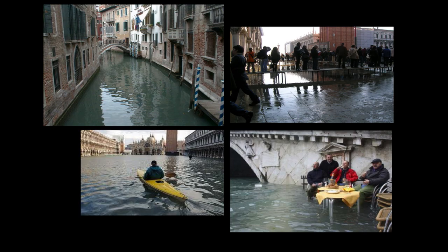Furthermore, the mud upon which all of these buildings have been built is getting compressed. Yeah, you can put down pilings and you can be very careful about your foundations, but at the end of the day, we're looking at a lot of masonry construction on mud. And over time, it's going to compress increasingly.